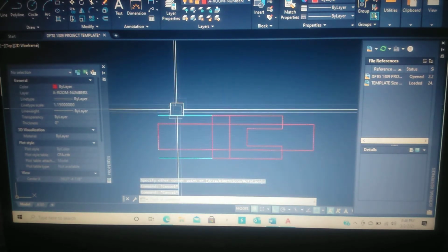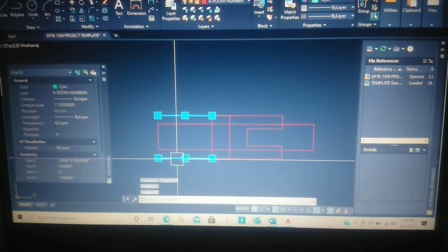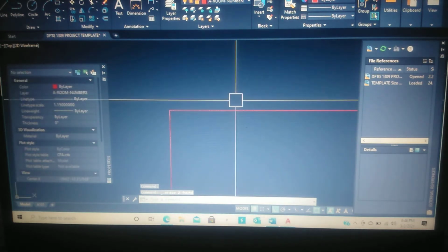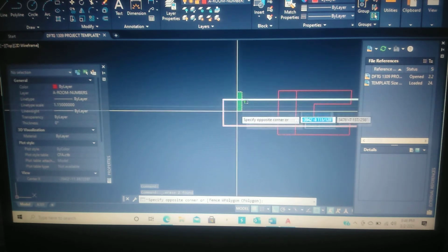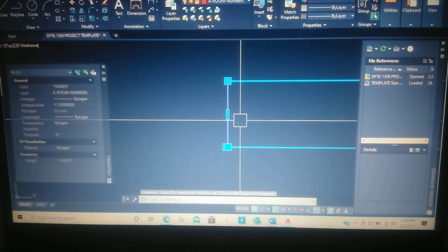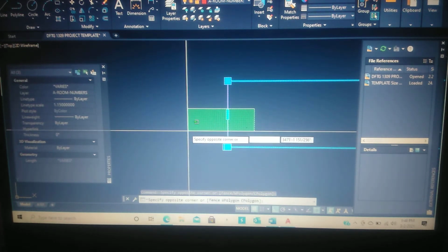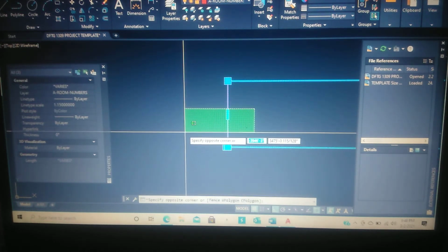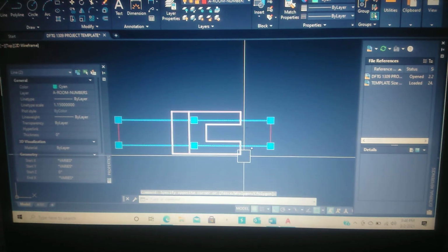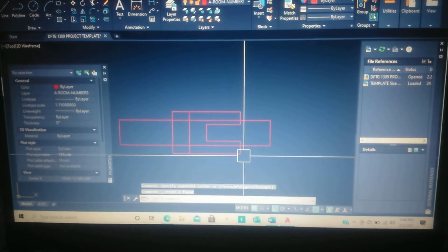And once your rectangle is drawn, you can delete this line, delete that line, okay? You probably can't see it, but if you want to delete these lines, you just select them all and then hold down shift and select the rectangle. When you hold down shift, this will deselect what you have selected. So the lines that are underneath it stay selected and you can delete them, okay?